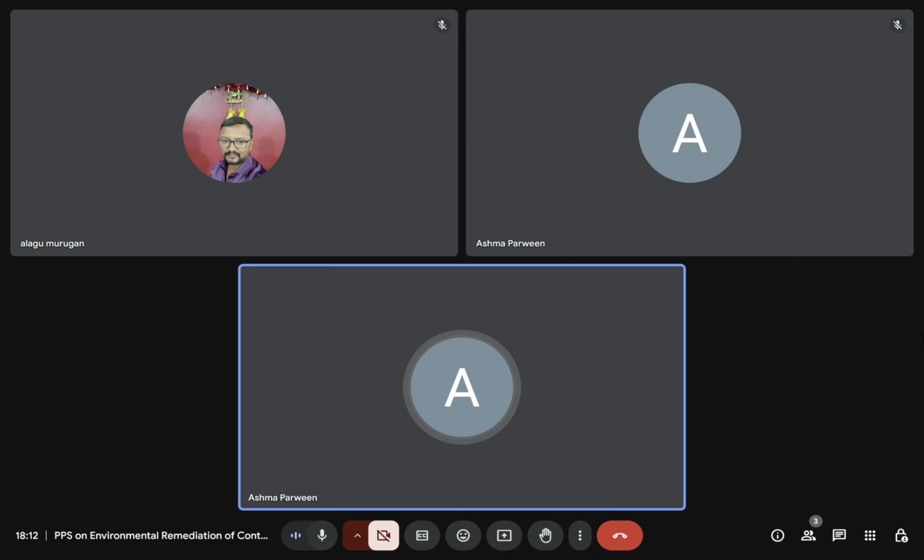So based on these, we discussed moving on to different methods. We also saw from the retardation factor that the time required to remediate the site increases when the contaminant is sorbed between the soil and dissolved in the water, and it increases further when there is some NAPL phase in the sediment.